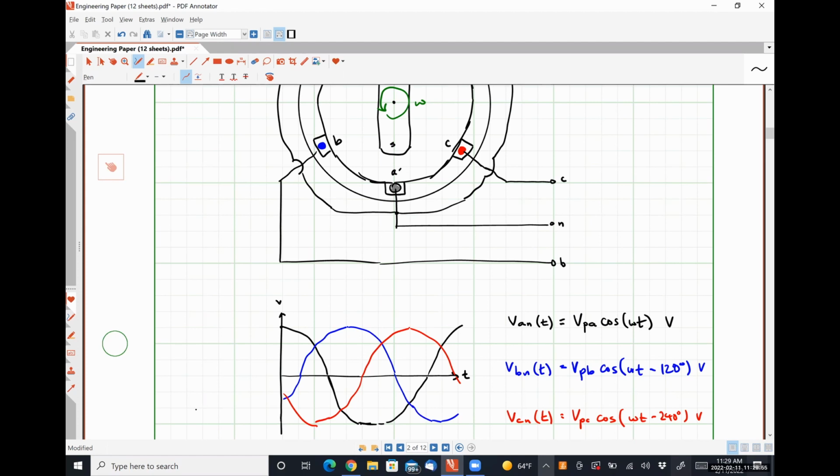So that's why I said yes and no. It's not really that you're getting a square wave and calling it a sine wave. You're taking parts of square waves and adding them together to make it look pretty sinusoidal with some harmonic oscillation, which does cause a little bit of vibration. But for your basic three-phase motor, like if we went into the power lab and hooked things up, what's coming out of the wall is a sinusoid, right?